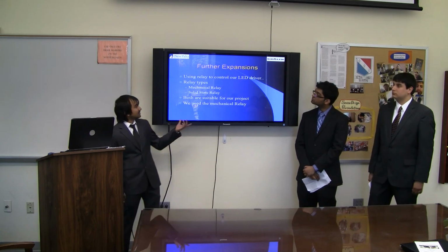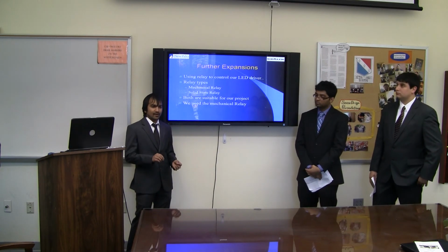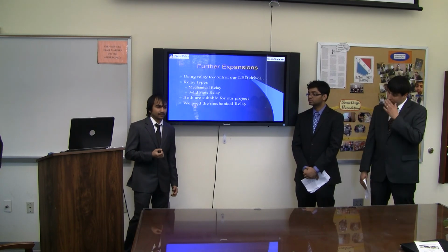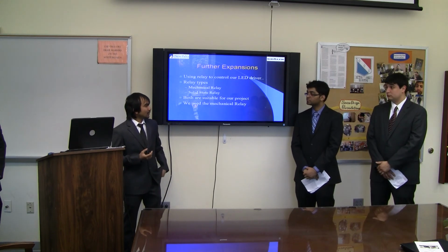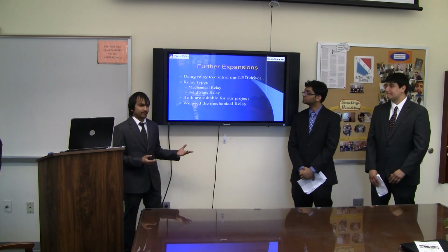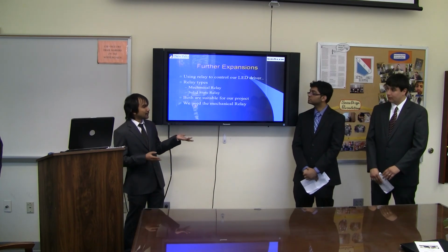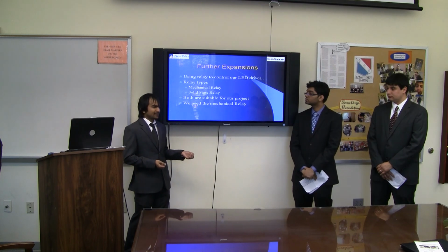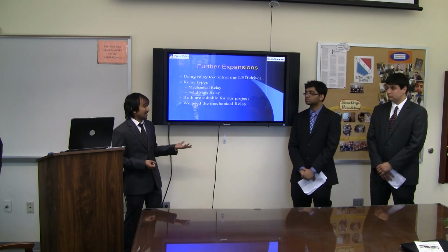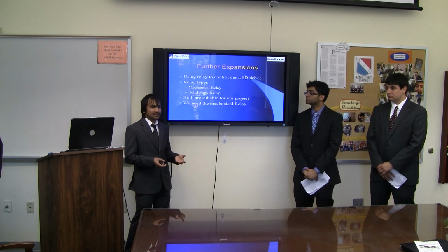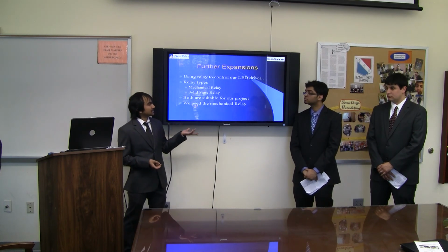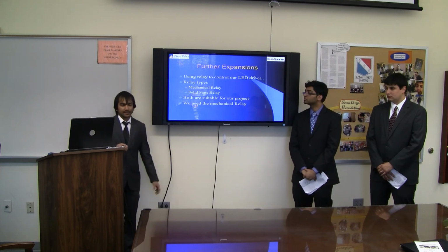After that, this is a further expansion, because as we said, one of our first aims was to get the data from the microcontroller to show in our Android application what the state is. After we accomplished that, we moved towards the further expansion that we earlier mentioned, having the ability to control any electrical device in a room. There are many relays in the market. Some of the relays are solid state, some of them are mechanical. Our application can work with both. It just needs a little modification. Using this application and relays, we can remotely control any electrical device inside a room.